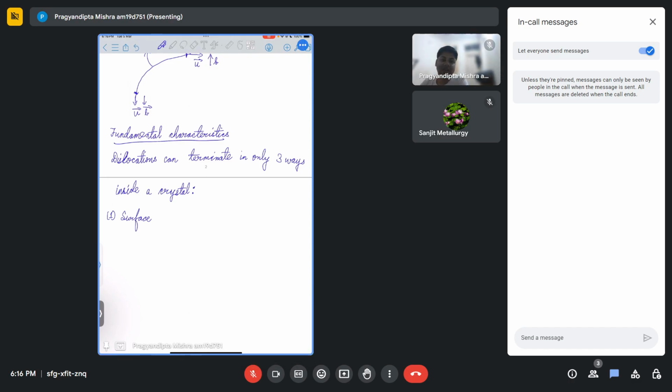So, if we are talking about the surface of a single crystal, it could mean that the actual surface of the entire structure has been reached. Meaning that if we have a 3D structure, right? Now the dislocation keeps going and hits this surface, like this face it has hit. So it has hit an actual surface, and therefore the dislocation has to terminate.